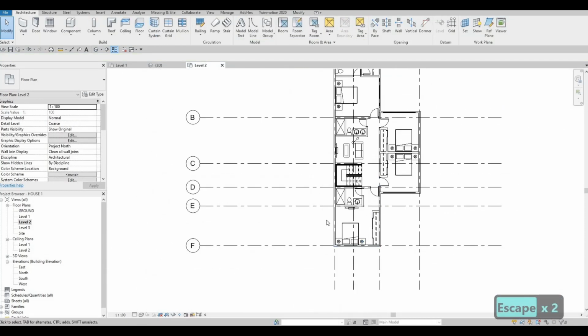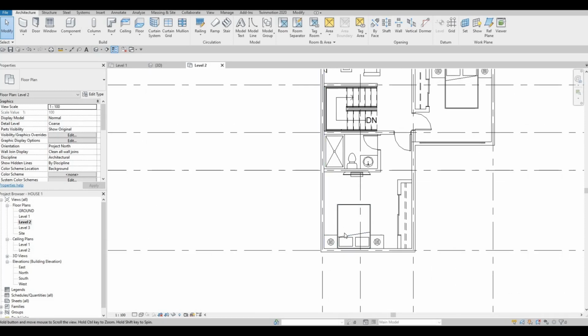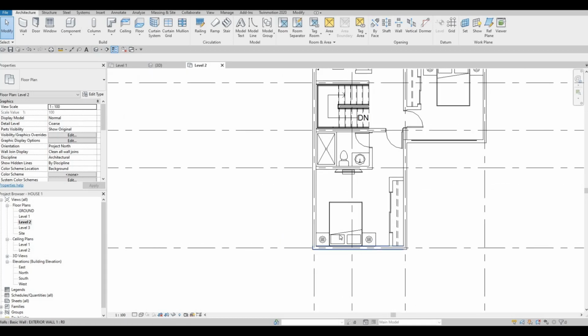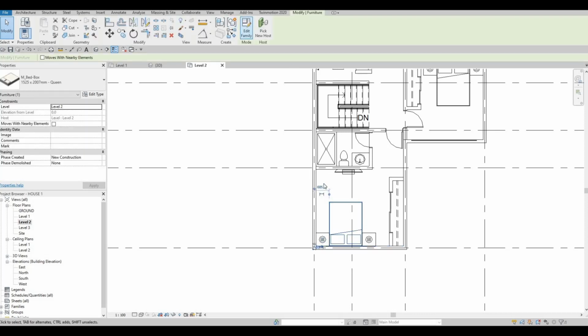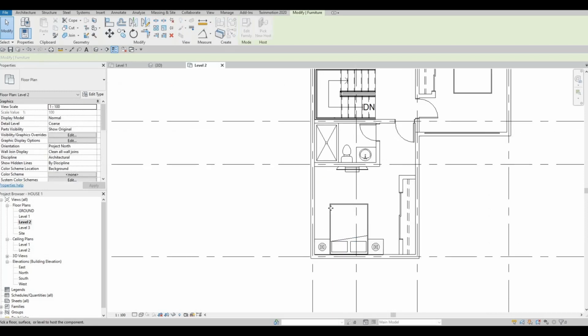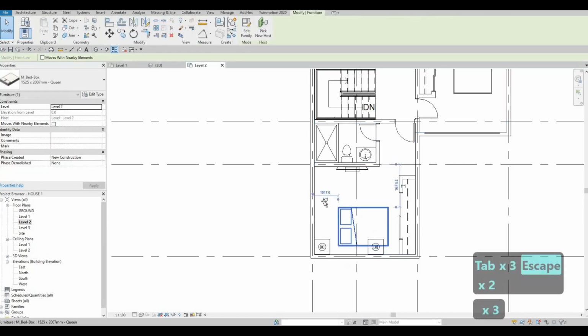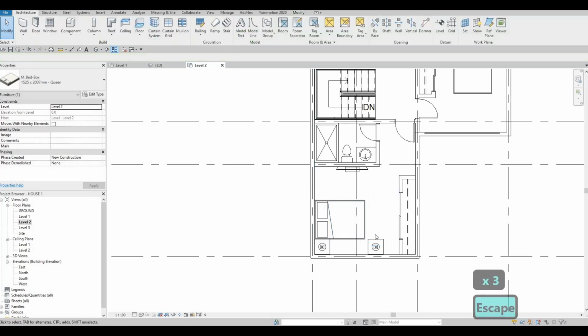So now, maybe I'm going to add here as well on this side. Or what we could do is flip this around. The reason for that is I like to add the window on this side, and it's a better idea. So I'm going to pick the new host. I'm going to select this, pick new host, or instead I'm going to press spacebar while selecting that, and I'll be able to add it like that.